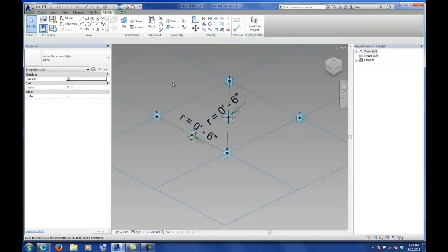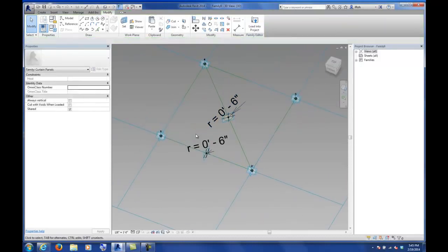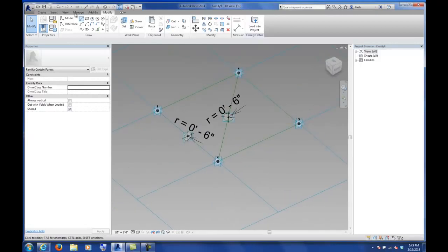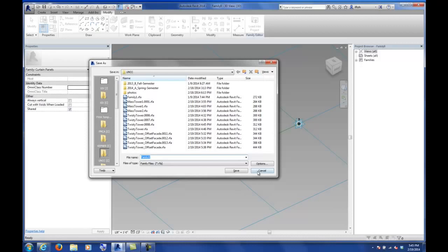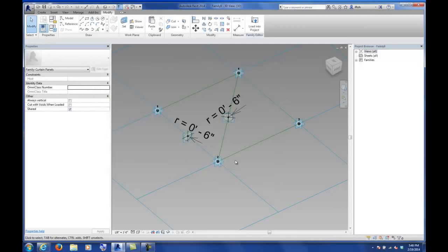What that allows us to do is later on when it's placed to the divided surface, if we decide 6 inches isn't the right scale, we can just edit this one time and change 6 inches to 3 inches or whatever we need. You got a question? Yes. We've set another length H, and we want the radius to be tied to H when we set it as a proportion of H. So you want like 2 radii? Yeah, like if you want R1 is always twice R2.